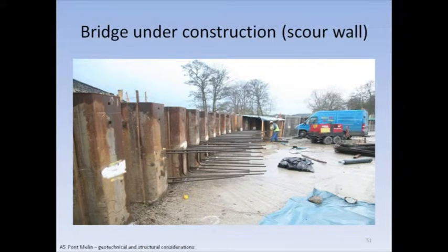The Environment Agency stipulated that once the pile wall was in, no construction works could be undertaken on the other side of that wall. And although there was a lot of discussion and requests to be able to do works on the other side, there was no ability to do that. So the conventional way to make an integral connection between the top of the piles and the base slab would be to have a capping beam with link bars going through the piles with holes burnt through.